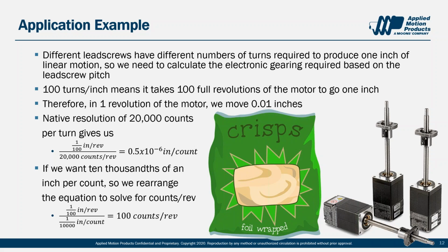Okay, so say you have an ultrasonic sealing machine with a linear stage that you're using to set the product height for a run of these small bags of chips. Maybe these chips are 5.06 inches tall, but this is a shared machine, and the next product you'll be filling are standard larger size chip bags that come in at 11.46 inches. It's advantageous to be able to set the product height in some easily understandable units, both to reduce PLC coding complexity and especially to aid the maintenance techs who are going to have to sift through that code later when some problem appears.